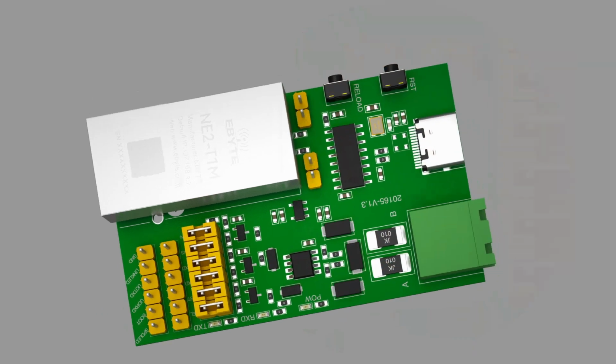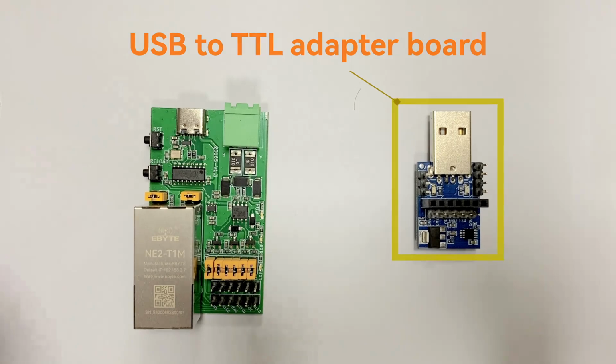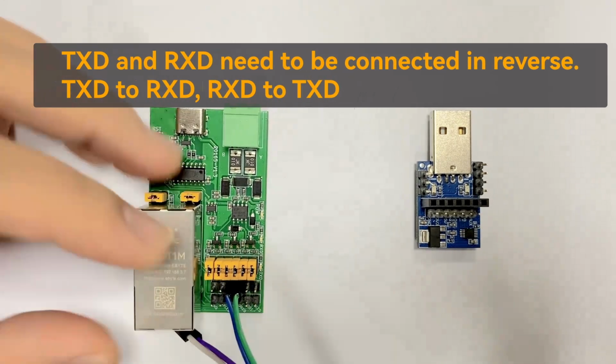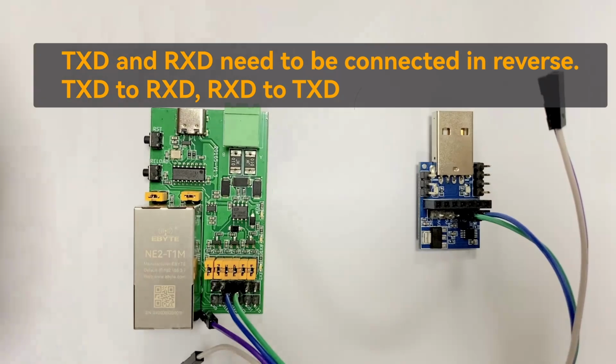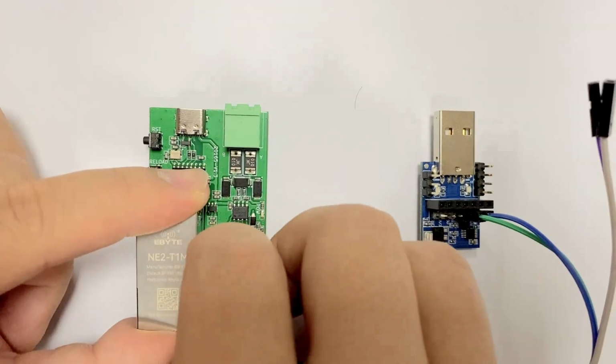In the demonstration, we will also use a USB to TTL converter, connecting the converter's TXD and RXD to the module's RXD and TXD, respectively. Next, use a power supply compliant with the product specifications to power the module.